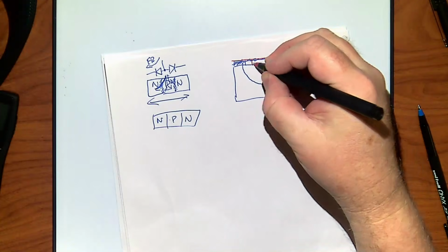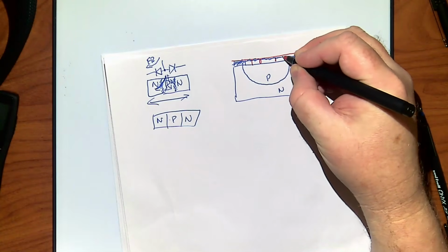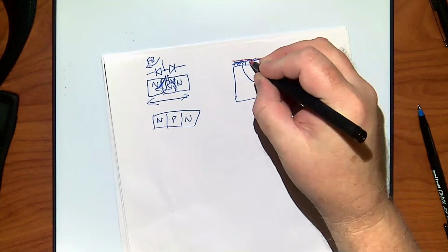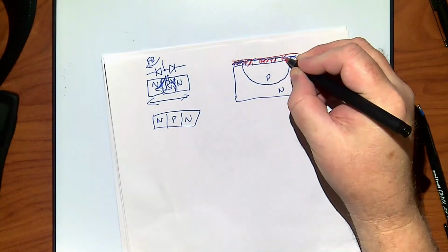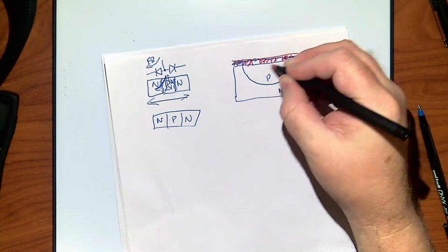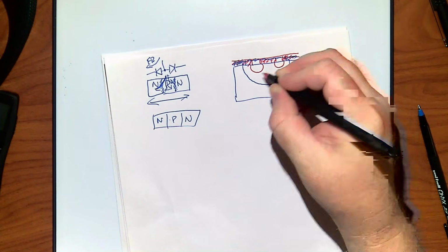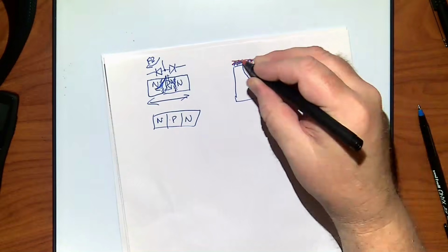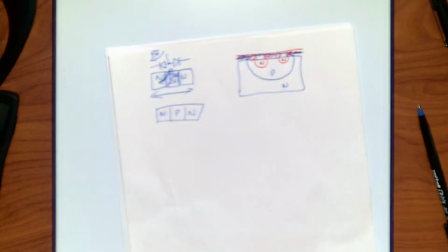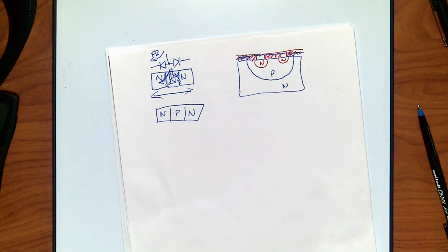But let's say I come in and again, I make two wells in here, right? And I get my resist, and it covers these. I remove the parts in the middle, and then I allow, again, this time N-type material in there, so I get two more little N wells, and I remove it again. See how I can, in a series of actions on here, do this. And then if I want to build up another layer, I don't have to put any resist on it. I can actually spin on material and things of that sort that has a particular dopant. And I can add a new layer to this.